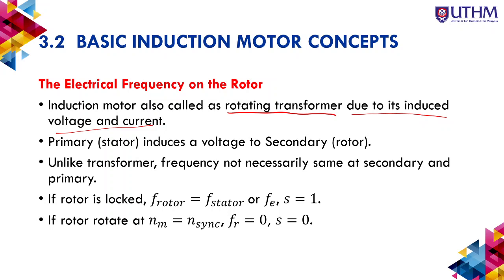Now imagine the motor is locked, which means not moving. So not moving, Nm is equal to 0. When Nm equals 0, S is equal to 1. At this point, the frequency of the rotor will be the same as the frequency of the stator.